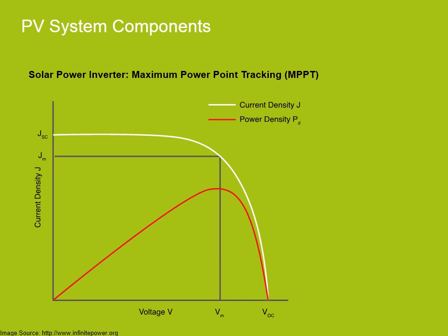most efficiently. Maximum power point trackers find the optimal power output automatically by finding the peak of the green curve, which represents power. MPPT ensures that you get the most power possible from your solar panels at any point in time. It is particularly effective during low light level conditions. These calculations result in an output that delivers maximum current at the required voltage at any point in time.